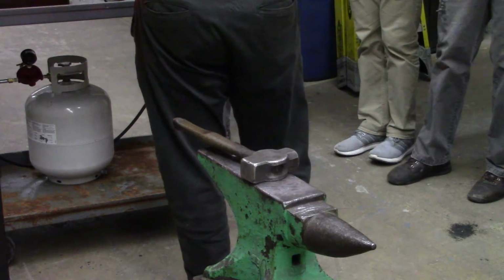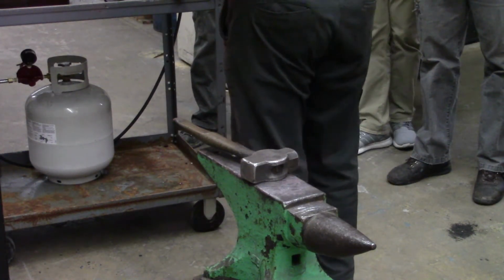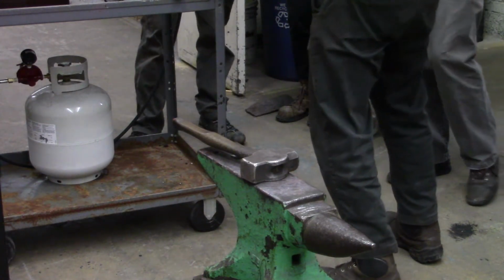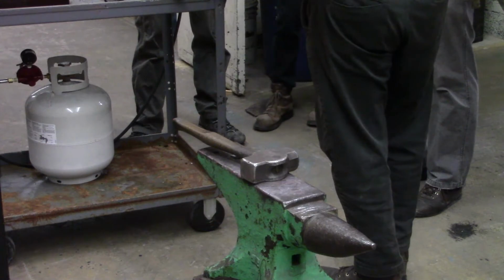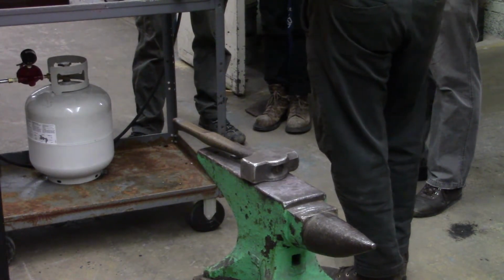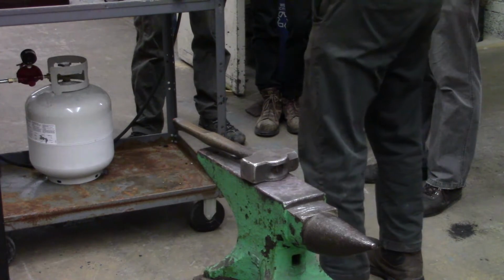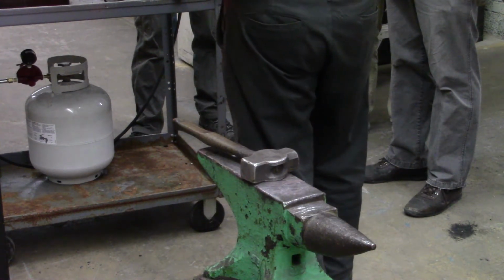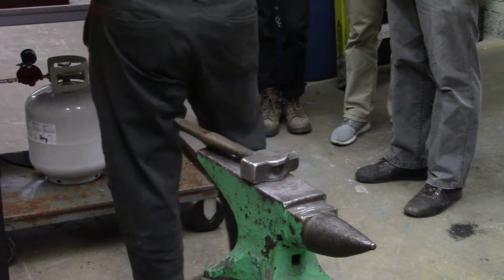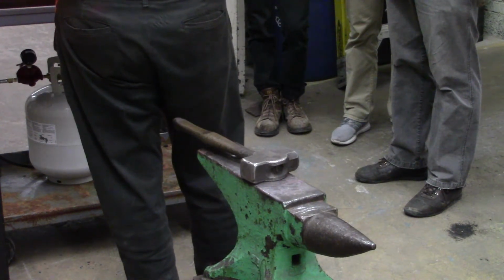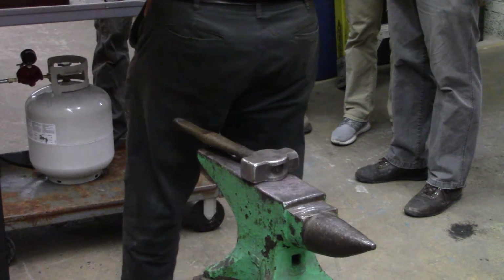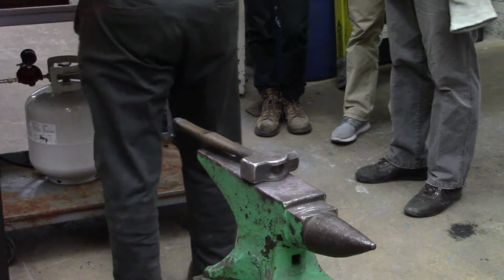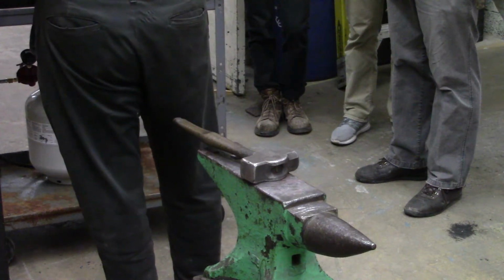What I did, you saw me grind those grooves into the billet. The billet has laminates that are straight. When you grind through and then flatten them, you reveal kind of a straight pattern. That's what I'm showing you there. Mine's probably not going to be quite as visually stunning as that because there aren't as many layers in the billet, but it's still going to be interesting. You can see the stripes in here even without much going on yet. The nickel stays bright even with the oxidation from these high temperatures, so you can still see it.